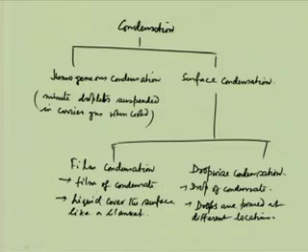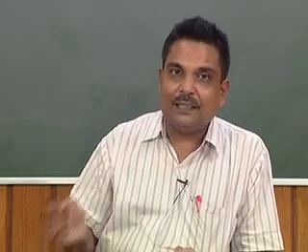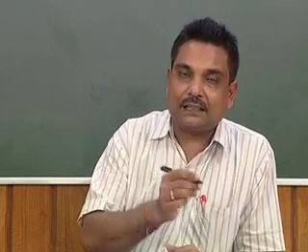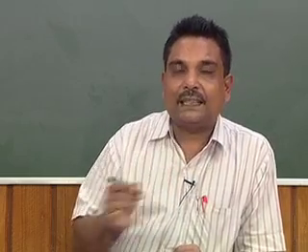And dropwise condensation is a very rare situation. It is the case when the fluid doesn't wet the surface, but it has been found that for a long time exposure, even the dropwise condensation behavior gradually or slowly gets converted into a film type condensation behavior.